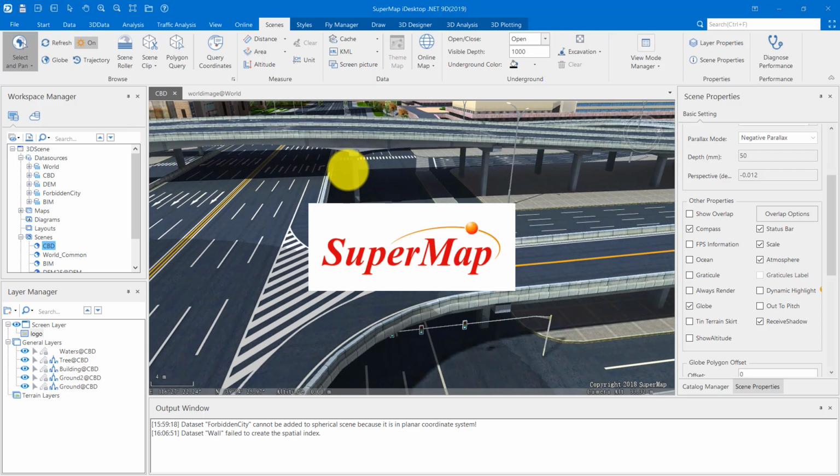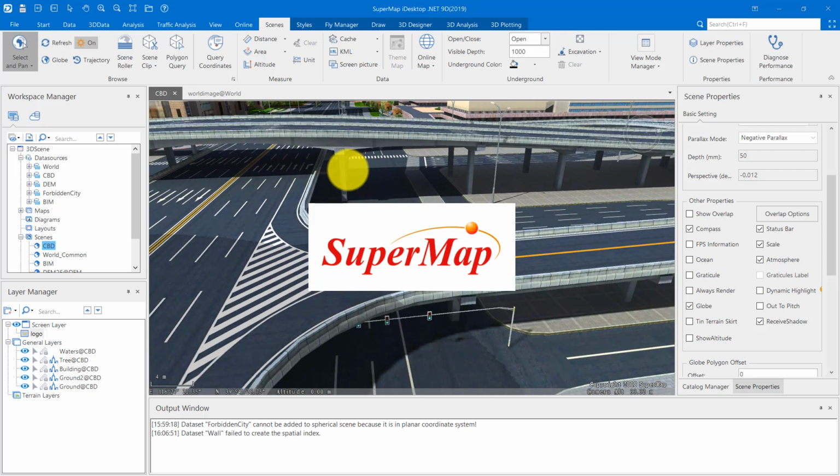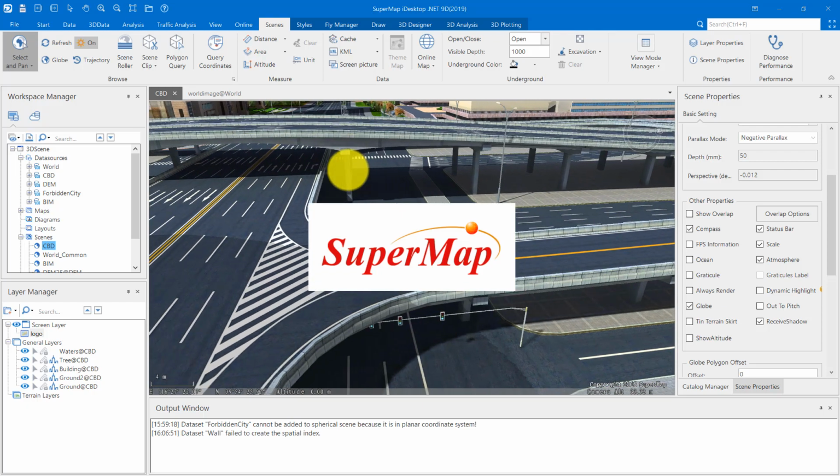Now, there we have our logo, but as you can see, I'm unable to edit it right now. That's because by default, we are selecting the elements on the 3D general layers. So in order to be able to edit this, we're going to right click on the logo image that we just added and enable edit. As you can see here, there's a small check mark next to it indicating that this object is now editable. You might also have noticed that we have some lines and pointers on the image now.